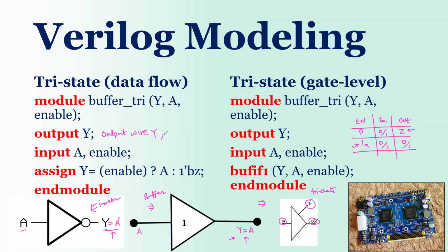Y. So you are basically specifying the output wire. This is another practice of specifying which one is your output wire and which ones are your input wires. But even if you don't do that, if you just say output Y, then semicolon, the synthesis tool will know, okay, this is your output wire. Otherwise, you specify explicitly that the output wire is Y.